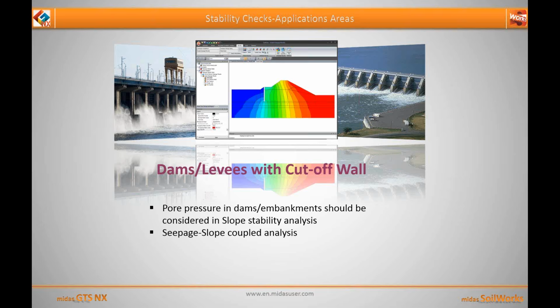So you should be able to perform the seepage slope coupled analysis so that you can consider the variation of pore pressure in the embankment or in the dam while considering the slope stability. So seepage slope coupled analysis becomes very important.